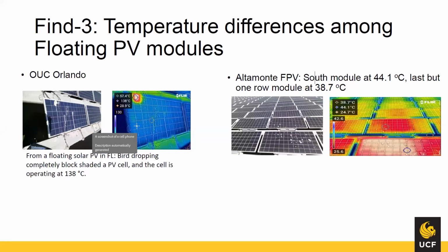Doubtful. That is more than likely a hotspot. Interesting. I'd be curious what's causing that then, because bird droppings aren't inherently hot over time. So just curious about that. But you're covering up over half of that cell, see that on the left side. You see that? That'll turn into a hotspot very quickly. But okay, yeah, I won't argue it. Trust me, it will.